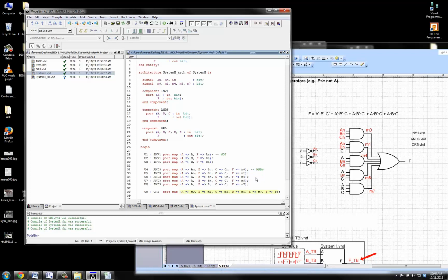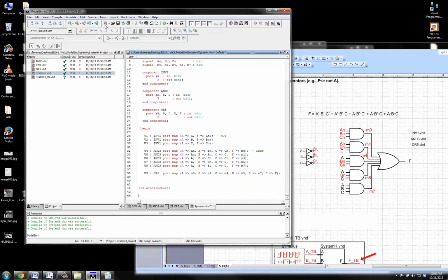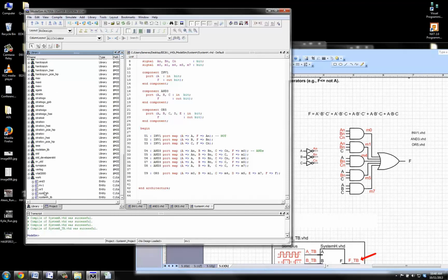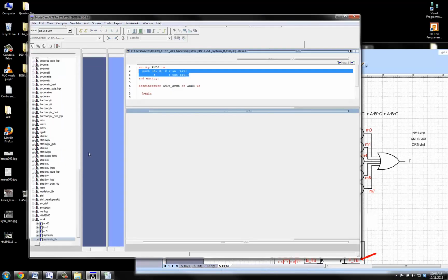Okay, that is it. So let's compile that up, make sure that I hooked that up right. And if I mess this up, I'll definitely see it in the simulation. Let's check this. M0, M1, M4, M5, M7. So I've got all those, they're all together, and architecture as we're ready to simulate. So I'm going to compile my test bench, make sure everything's cool. We're ready. Let's go into my library. I expand work. I load. Now look at all the things that have been compiled now. We got more things. We load the simulation though, always by double-clicking on the test bench.